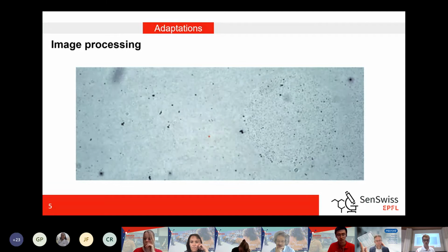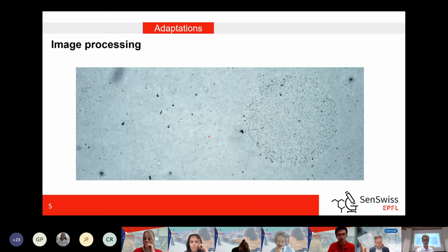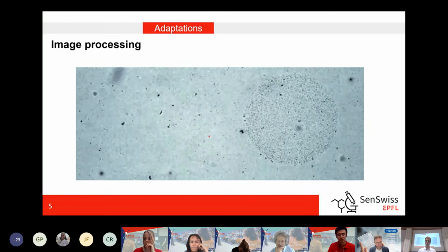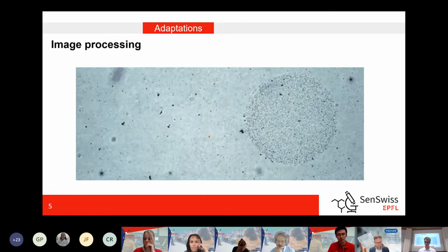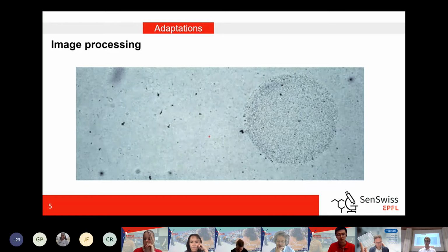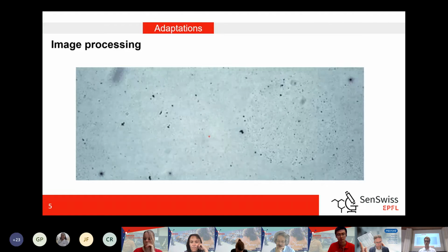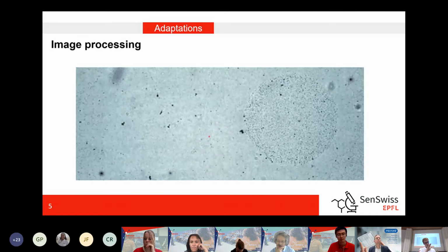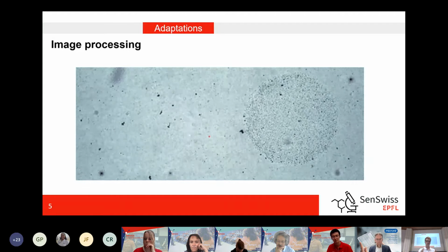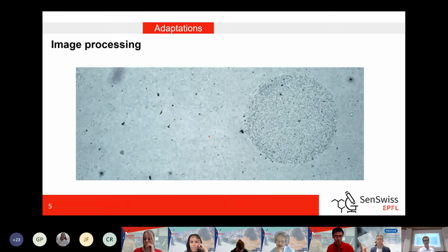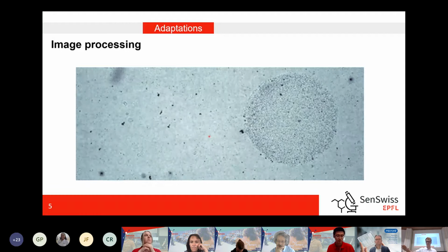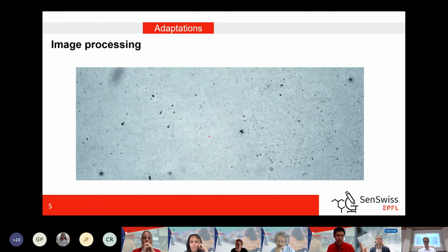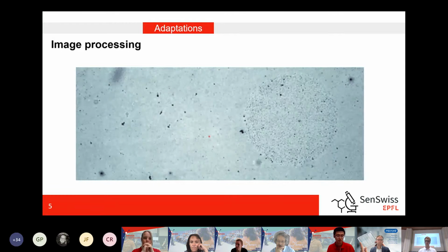As you can see, the spots are quite dark in comparison to other noise you can see on the image. So the first thing we do is threshold the image to binarize it. Since we have a flow, we also use a median filter. We take 5 images, and each pixel is ranked based on intensity, so that if, for example, a little bubble passes, the median filter normally gets rid of it. So we don't have that problem.